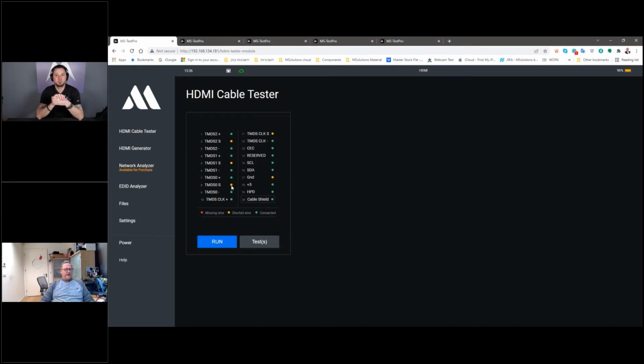So it is good, it is bad. There are situations, this, by the way, will limit you with frequencies. The moment that the clock frequency increases to high frequencies, I would expect that the noise from the clock will be injected to the GND here. Because you need to understand, all of those are actually floating power supplies. So there are pros and cons for each type of methodology that is being implemented.